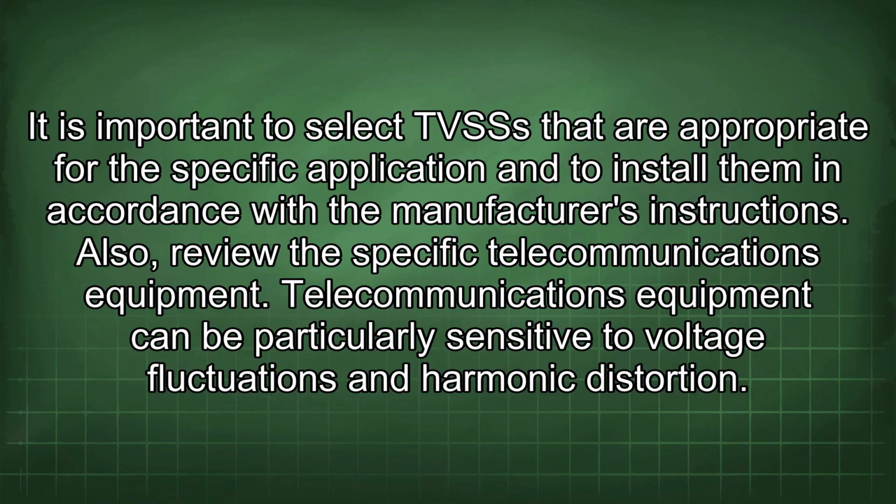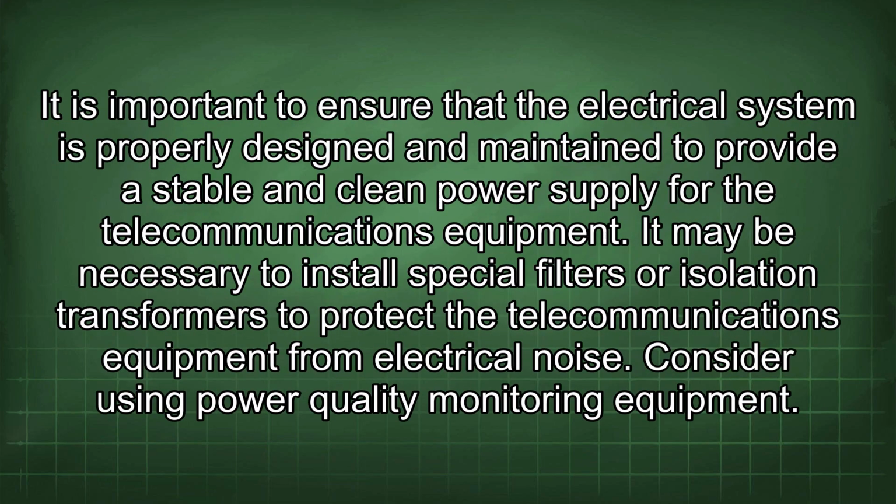Also, review the specific telecommunications equipment. Telecommunications equipment can be particularly sensitive to voltage fluctuations and harmonic distortion. It is important to ensure that the electrical system is properly designed and maintained to provide a stable and clean power supply for the telecommunications equipment. It may be necessary to install special filters or isolation transformers to protect the telecommunications equipment from electrical noise.